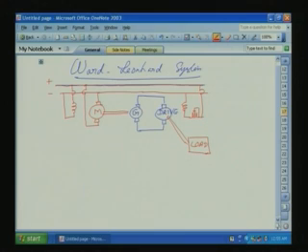Now, there is a generator. This generator supplies the variable voltage to the drive. So, how do you get a variable voltage here? For this generator field, again we can control through a resistance. We will connect it here. So, the machine is running, our motor generator set, motor and generator. This motor is running at constant speed. Now, by controlling the field excitation of the generator, variable armature voltage can be given to our drive motor.